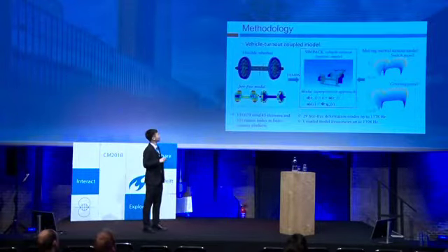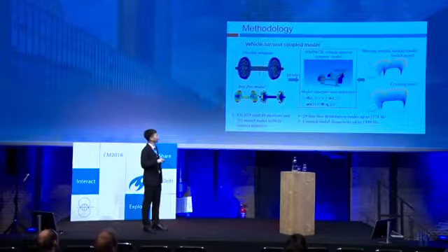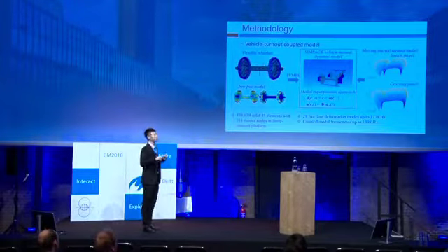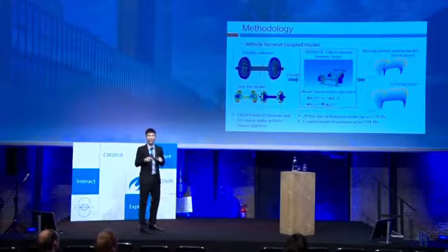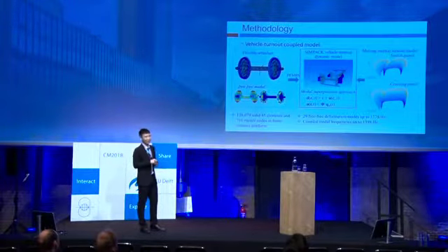As far as the methodology, the Simpack software is used to build the vehicle model. In order to consider the precise contact fixation and creepage, the flexible wheelset is used. And after obtaining the free model of the wheelset based on the finite element platform, the flexible wheelset is employed in the vehicle model via the FEMBS interface.